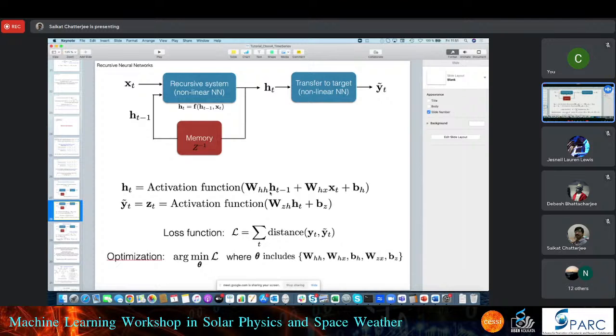It is also used for localization in your mobiles or GPS systems. To localize at a particular time, you have measurements through the base stations, which possibly Google collects, and then it tries to predict what will happen in the next time instant, and then it corrects according to that measurement. That's what the Kalman filter does.